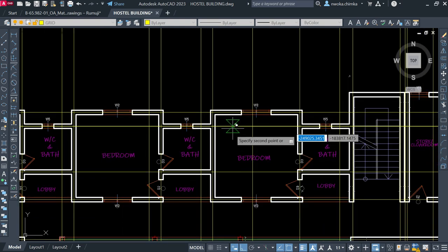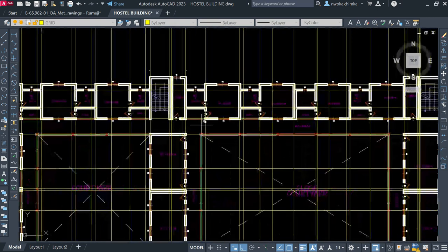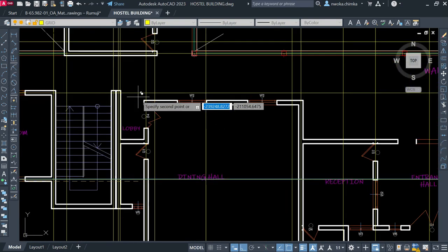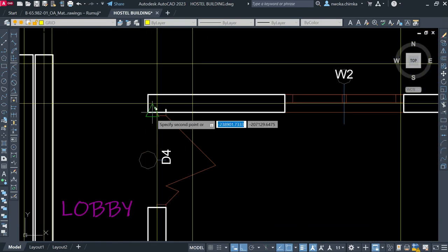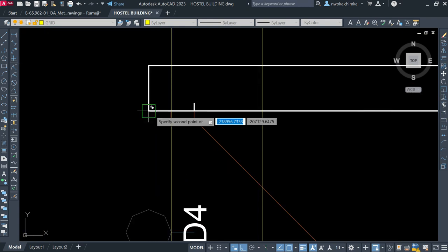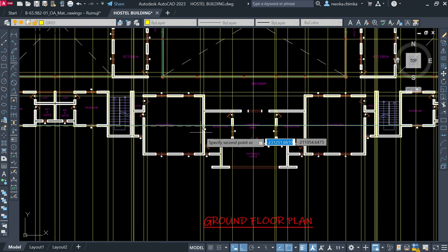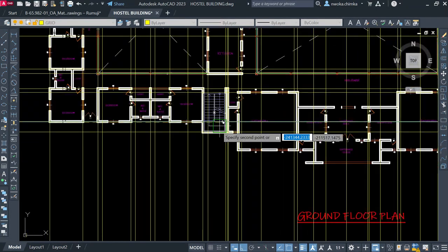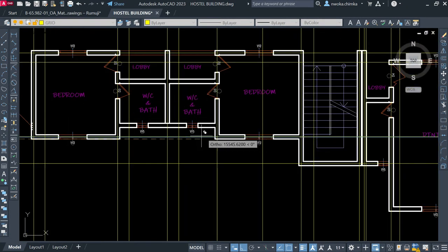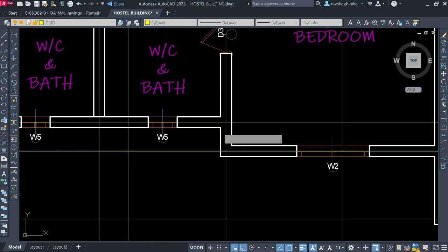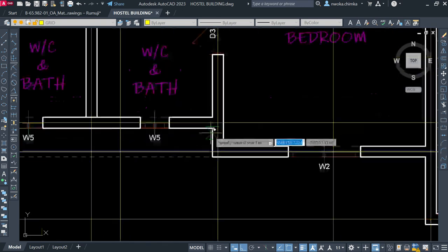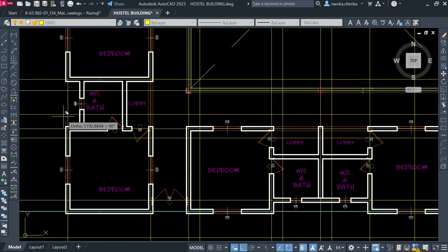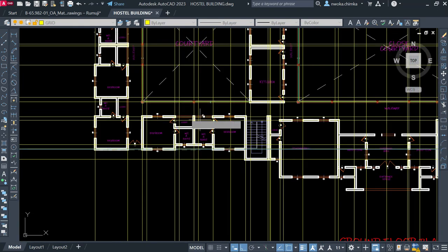Okay, and then if I'm done placing all my horizontal grid lines and all that, next thing to do, I'll also locate this. This is not yet placed. I'll place this here. So you have to spend all the time to make sure that you have done all what you're meant to do to place all your grid lines. Because when we enter Prota Structure, if you don't do this, then you will see that the time you took preparing your modeling will take much longer.